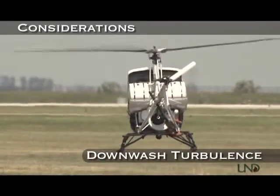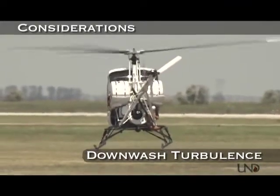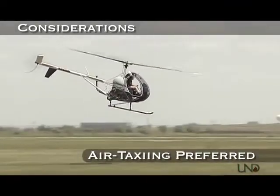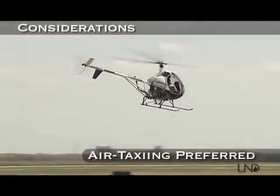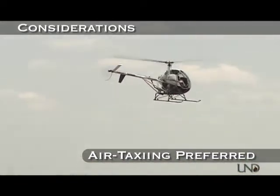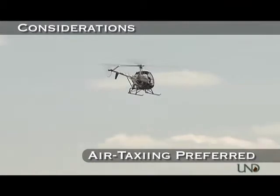Now let's look at some of the special considerations to keep in mind when dealing with helicopters. The first thing to keep in mind is that helicopters can produce downwash turbulence, which we talked about in the last segment. Another consideration is that air taxiing is usually the preferred method of moving helicopters around the airport surface. For one thing, it minimizes the effects of downwash turbulence. Air taxiing is also faster and more fuel efficient.